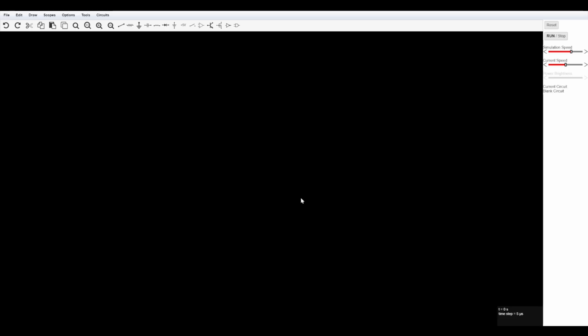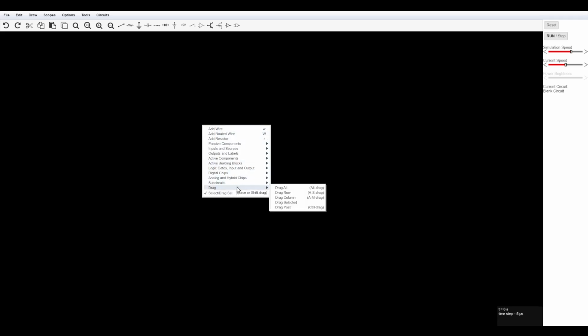All right, now in Falstad, we actually have some other options because we can make sub-circuits and essentially build our own ICs. But let's see what we have naturally. Analogs, we've got a couple of different things. 555 timer, phase comparator, and we've got our digital analog stuff and VCOs, monostable. These are, again, generic models, but you can find chips that are this plus more.